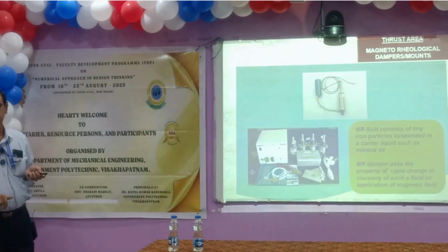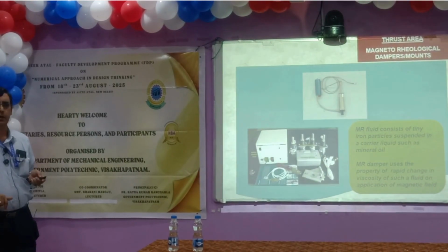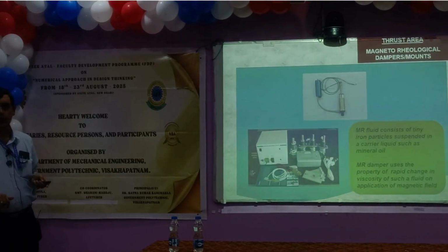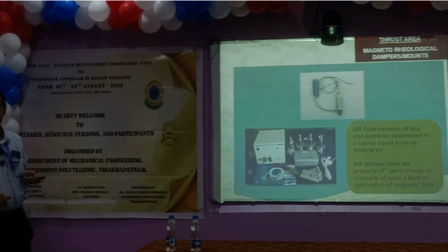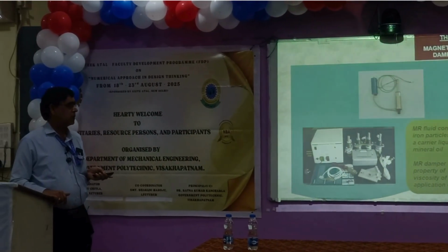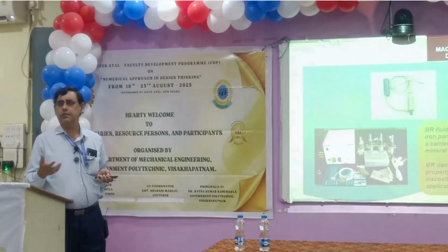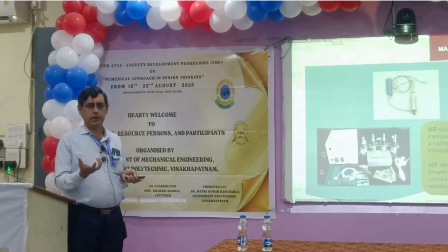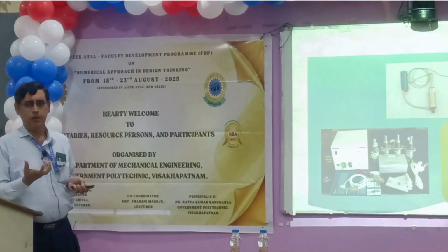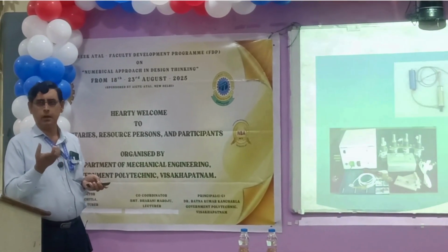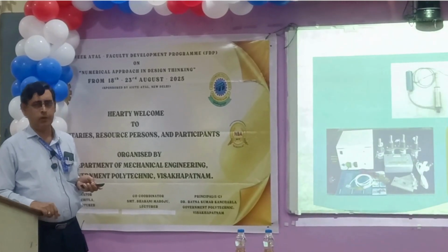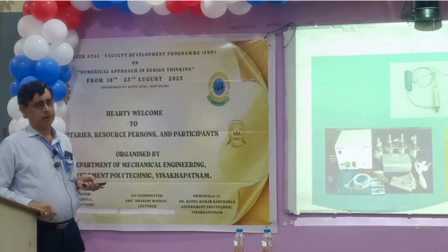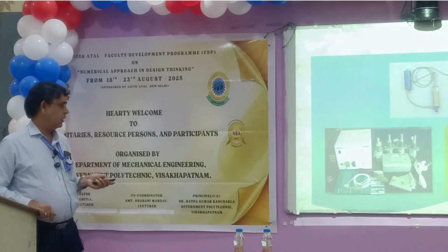And the latest one is the active control, as I mentioned. This is an application of active control. This is a magneto-rheological damper mount, we call it MR mounts. Rheology is basically the study of viscosity. Magneto-rheology means you are applying magnetic particles in a liquid to get viscosity changes in the liquid, so that it basically changes the pattern of vibration.